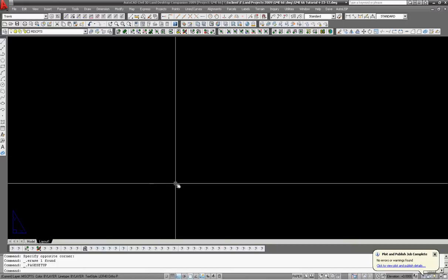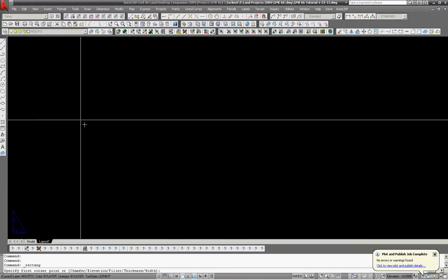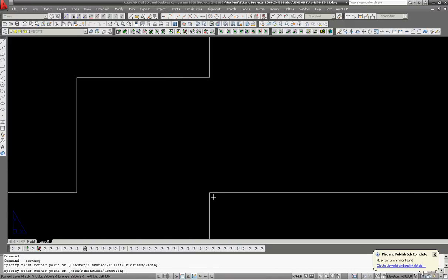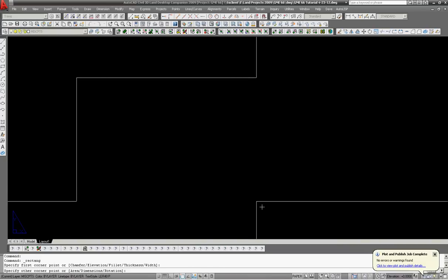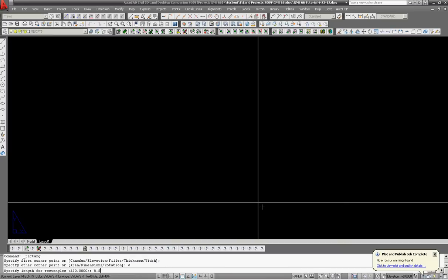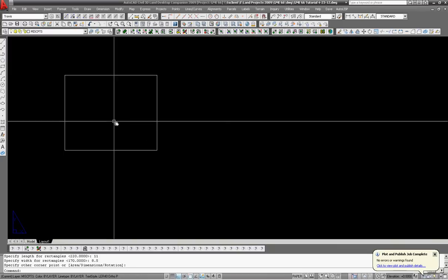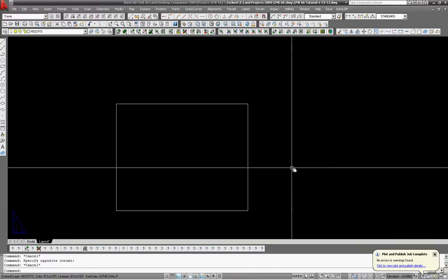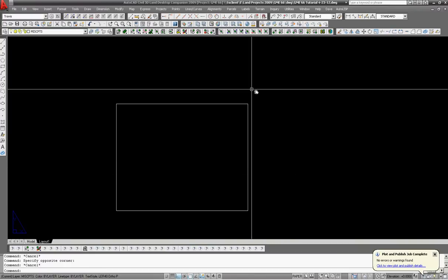Okay, so now what I'm going to do is create a box inside here. I'm going to click here and make it the dimensions of my paper. So 8.5. Oops, sorry, I have to do dimensions D. Here we go, 8.5. Well, let's start with 11. 11, 8.5. There we go. All right, so now this is the size of my paper because I'm going to use the units in my paper space as inches. If that makes sense.